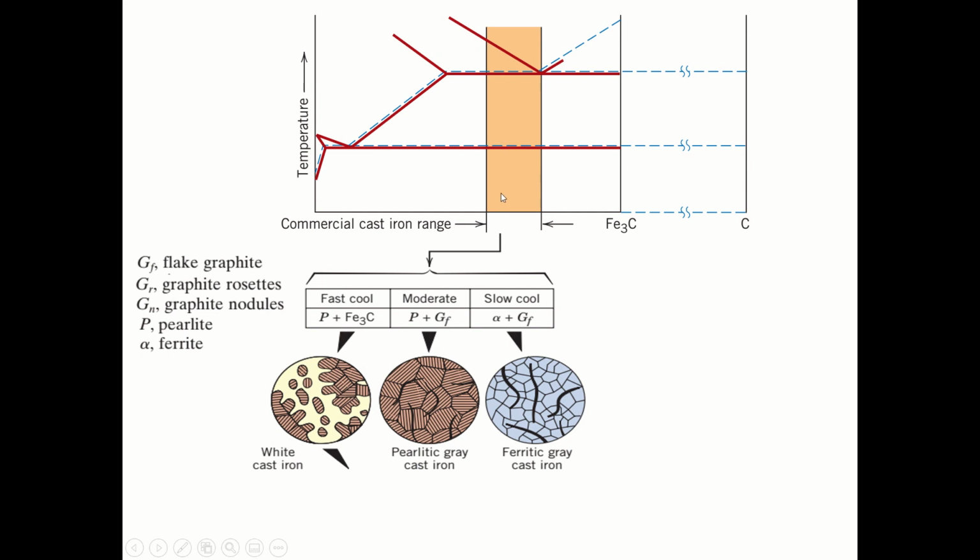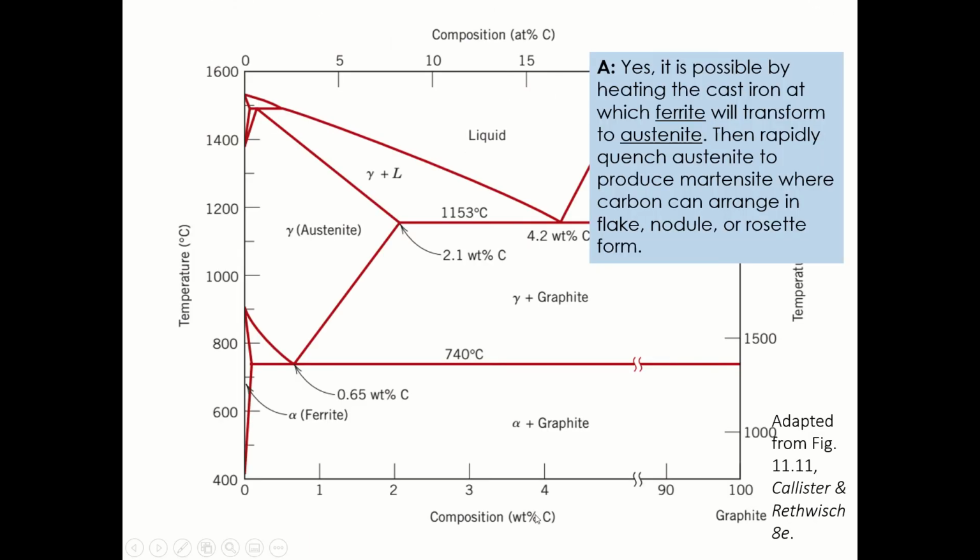This is important: you can only have this kind of property if you use a ferrous metal alloy that has a carbon concentration around here. So these are the treatments. If you heat them at this concentration at different temperatures, going back here, if you heat them at 600 degrees Celsius, you will only have ferrite.